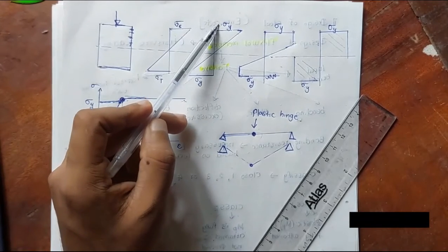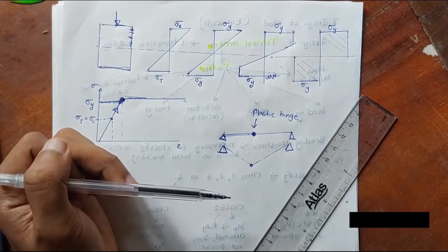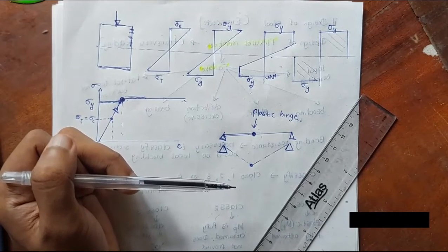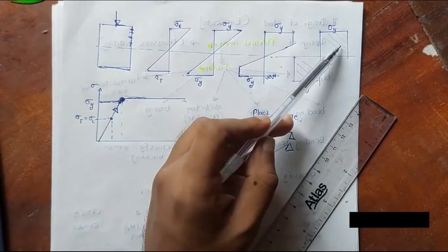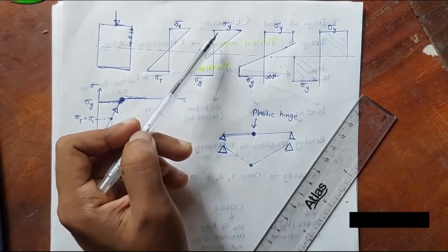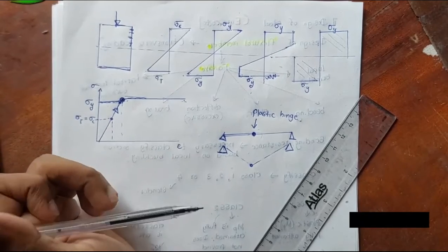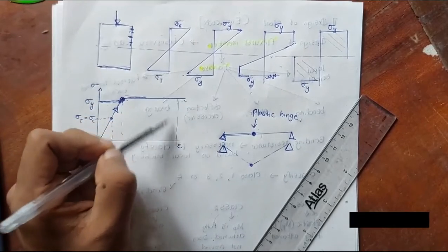Because in the elastic state we have a warning, right? Your stress is at maximum, and then the failure is going to be a ductile behavior, right? So it gives a warning, right? But actually the disadvantage is the material has a capacity beyond that. We are not entirely using that for the design, right?